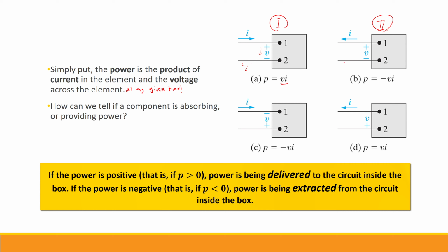However, the direction of the current has changed. Because now the current is flowing through the terminals in the direction of the voltage increase, based on the passive sign convention that we have, we use the variable with a negative sign.